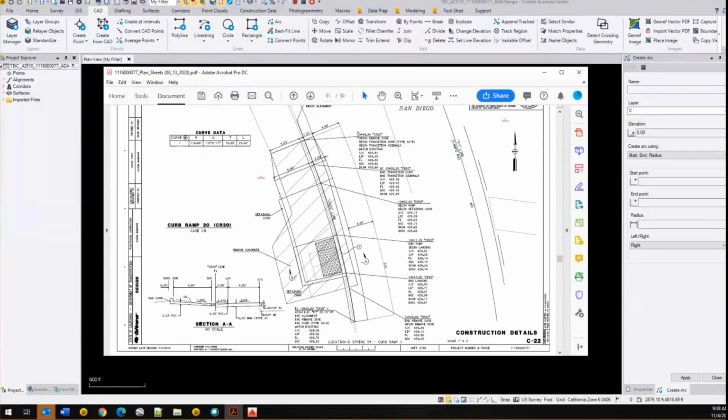Another thing about this is all of the grades are being given as callouts at the station. Some of these designs will have a table, which I find very difficult to use. So I'm glad they went with this route and doing callouts like this. We've recently been working with design on another way of presenting return data where they actually put the slopestake notes on the detail sheet. But this is the most common one I think I found for this work.